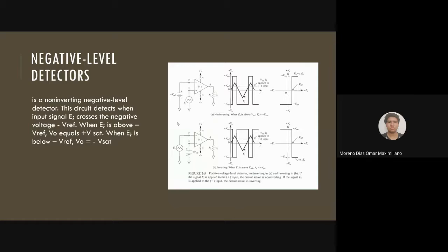The basic configuration for the positive voltage comparator, also known as the non-inverting comparator circuit detector. When the input signal voltage Vin is above and more positive than the reference voltage Vref, the output voltage Vout is high, as shown. Next.